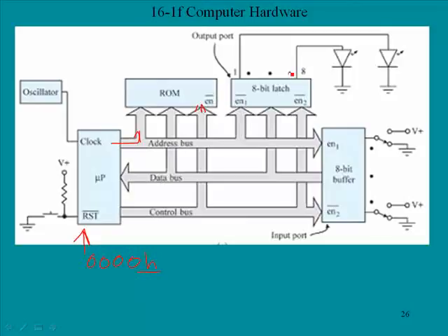The microprocessor then increments the program counter and fetches the next byte by sending the program counter to the address bus and again activating enable on the control bus. Down the data bus from ROM comes our command, 00000001, since that is what we put there when we wrote the program. The microprocessor takes this byte and stores it in a temporary latch internal to the microprocessor.